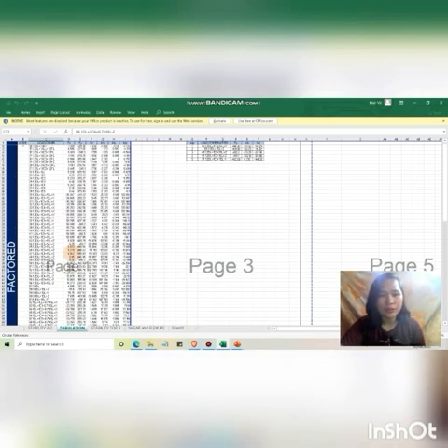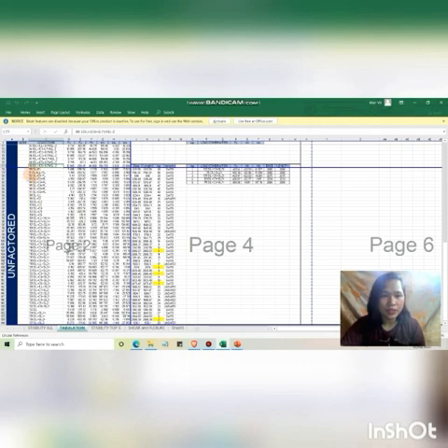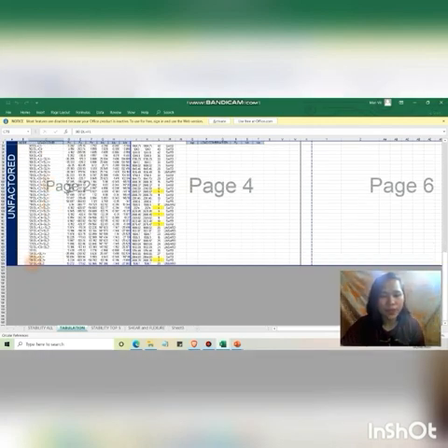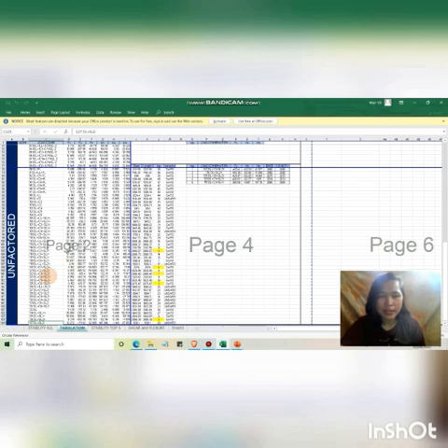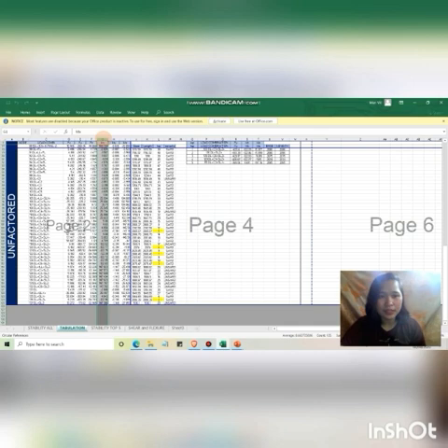In the first table, we can see the factored load combinations, numbers 14 to 89 here. From this factored load, we will choose later the top 5 for our calculations for the shear and flexure. Now, below are the unfactored load combinations, from 90 to 137. We will use these unfactored loads for our calculations for the stability, or for the dimensions of our footing, the base and the length. In our calculations, we will use the PY or FY here, the MX for our moment at the X axis, and the MZ for our moment at the Y axis.